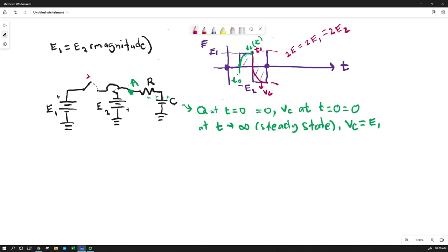Because that's a little bit confusing sometimes when we go from our initial derived expression for a single voltage step, closing switch 1, we can derive our expression for how the voltage drop over this capacitor changes with time. We can create that expression for the transient. But then when we go to our proto board and we impose a square wave voltage, which is really the easy way to confirm that in a real circuit, sometimes it's a little confusing when we suddenly have this double amplitude, and we've already charged up the capacitor, and now we're looking at it discharging through what's basically twice the voltage drive. So we're going to step through that.